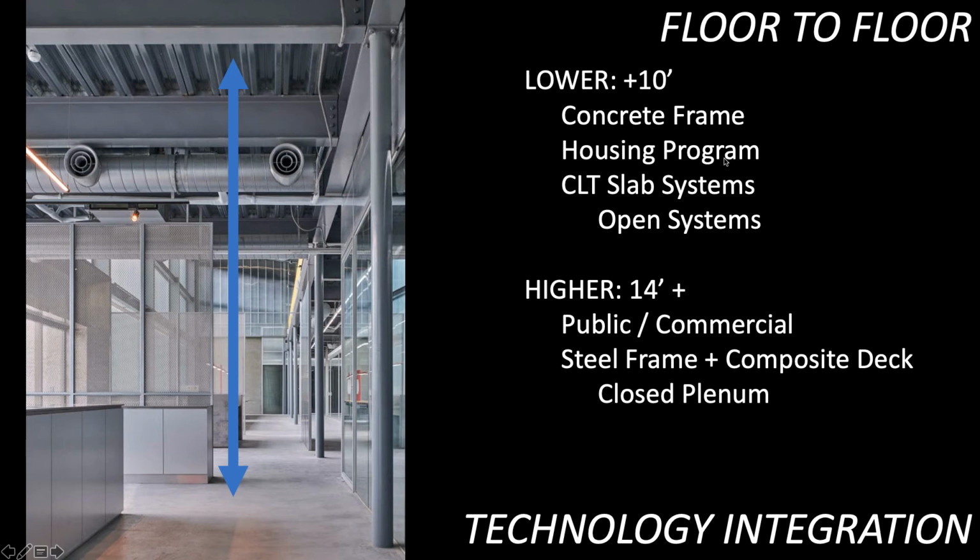In a housing program, we also have the reduction of a lot of centralized ductwork. With our CLT slab systems, if you have your column spacing close enough, you can go straight to a slab even without a beam, which is kind of miraculous. And in cases where we have open systems, we may also expect slightly lower floor-to-floor. It's not always going to be this low, but I would say that's kind of your minimum, and we work up from there. 10 feet floor-to-floor is absolute minimum, probably only appropriate for a housing program.